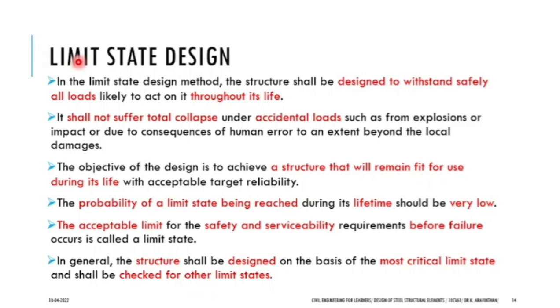Okay. Now in limit state you are saying, if you want to build your structure, my structure is going to take all these loads. So what are the loads which will be acting on your structure? You list it out one by one. What are the loads? Dead weight, that is the self weight of the structure. Then live load. The live loads can be the table, chair and the humans. All the things come under the live load. You have to consider live load.